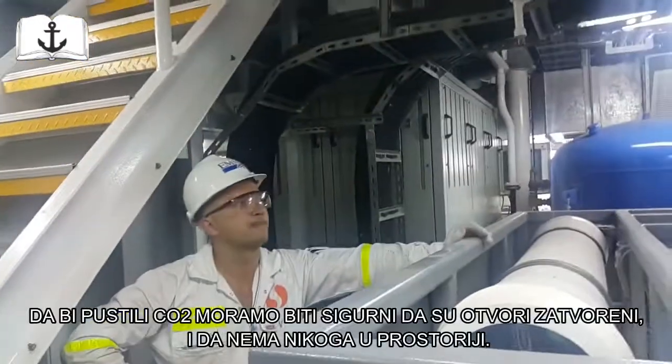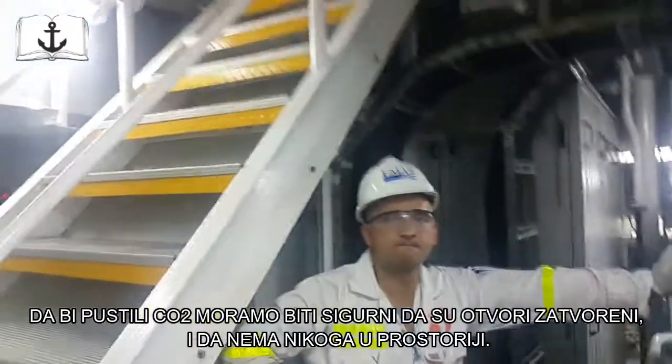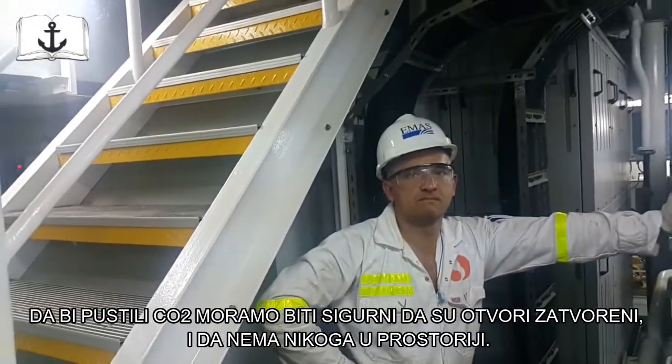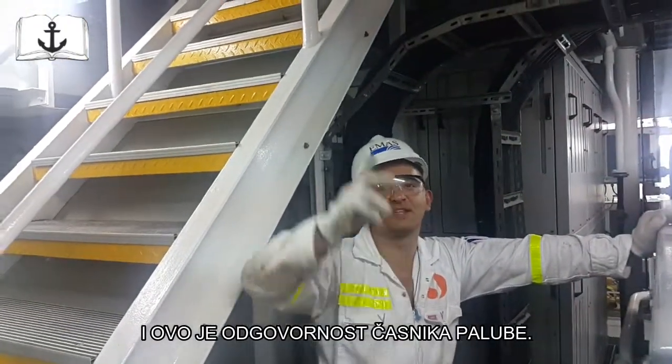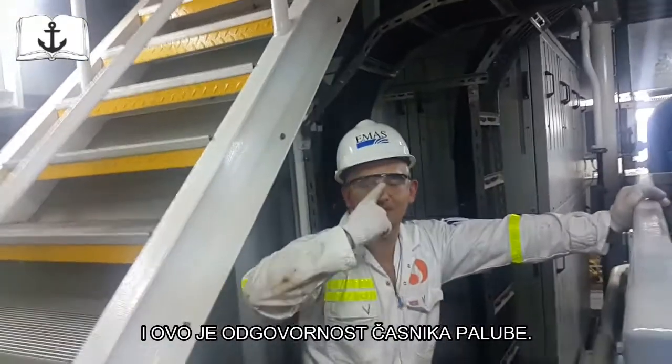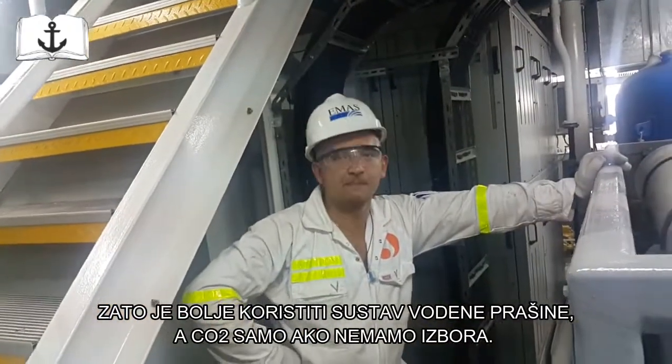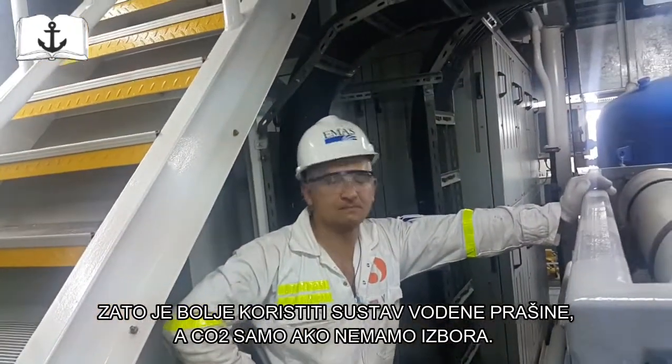So, to release CO2, you need to be sure it's all closed. You need to be sure there's no one in the room. And this is your responsibility. That's why you have the station on the beach. So that is why it's better to use water mist, because CO2 should be the last resort.